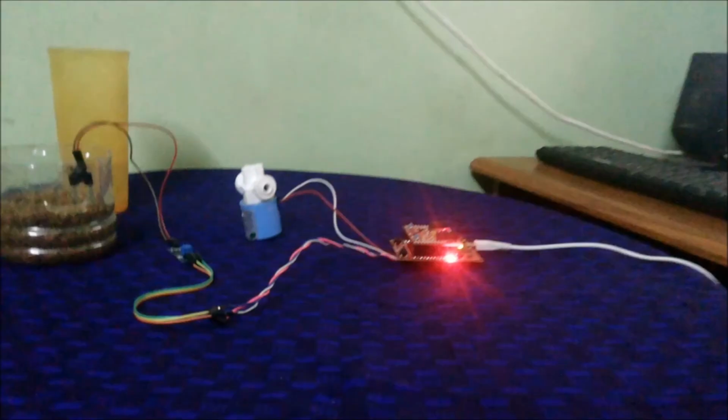A moisture sensor is associated with Stellaris launchpad. Each subsensor is periodically interrogated by a pulse signal provided by the microcontroller via a driver or buffer circuit. This interrogation signal causes the moisture sensors to output an analog voltage which is proportional to the amount of moisture in the soil in which the sensors are embedded. The moisture sensors then respond by transmitting the aforementioned electrical signals to the microcontroller. Thus, the microcontroller activates each of the valves